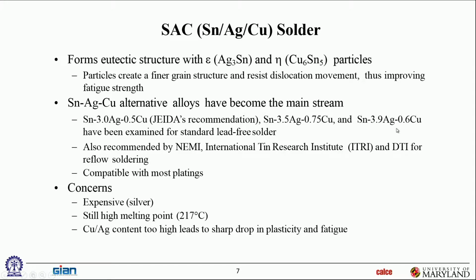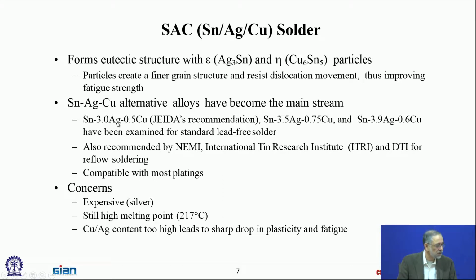to silver. So for a variety of reasons, some environmental, some cost, some life cycle considerations, the percentage of silver has slowly been dropping. Especially in portable electronics, it turns out that the drop resistance, ability to survive drops, correlates very closely with percentage of silver. That means how much silver tin intermetallics you have. Less silver tin intermetallics usually translate into better drop durability. And not to mention portable electronics is slowly getting cheaper and cheaper and cheaper. So the cost of silver also has to come down. So they're down to fractions of a percent of silver already.